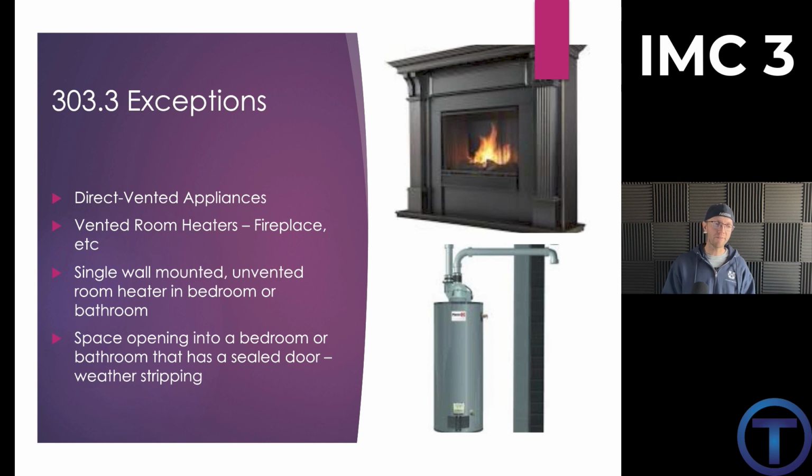Single wall mount unvented room heater for bedroom or bathroom, or a space opening into a bedroom or bathroom that has a sealed door or weather stripping. Putting in a door, so maybe this is my bedroom, but there's a closet here with my furnace in it, but it has a sealed door that is not going to affect the air that I'm breathing or leak any sort of exhaust gases into that space.